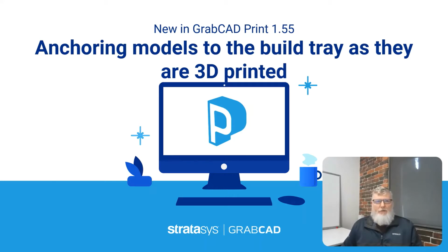Anchors are support structures used to improve print quality. On thin, wide models, or models made from materials susceptible to curl like Nylon or Ultem, anchors secure the bottom face of the part to the build tray. Anchors may also be used to secure downward-oriented faces of the part to upward-oriented faces. When toolpaths are generated, support structures and base features will adapt to the anchor feature, ensuring that the model is securely fastened to the tray.